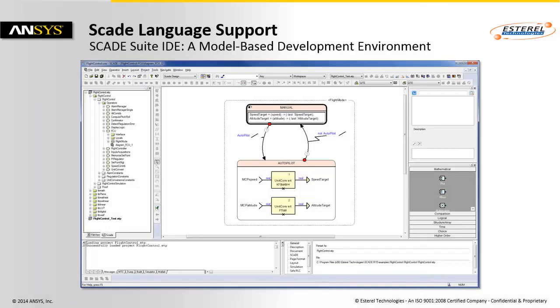The SCADE Suite Integrated Development Environment is a model-based environment dedicated to the SCADE language. Its editor fully supports the SCADE language, as it recognizes each language construct and its proper use. Within the SCADE Suite IDE, the user can edit and check SCADE models, perform traceability with requirements, perform model-based simulation and formal verification, perform model and code coverage, and stack and time analysis. And finally, he can generate code that will be embedded into the final system.